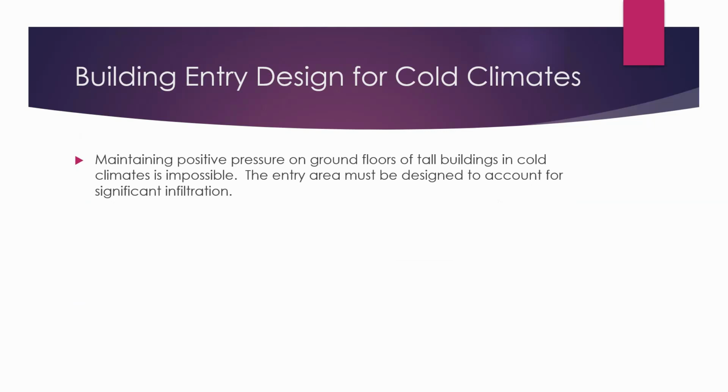Maintaining positive building pressure on the ground floor of tall buildings in cold climates is impossible. The interior must be designed to account for significant infiltration. So what do we do?